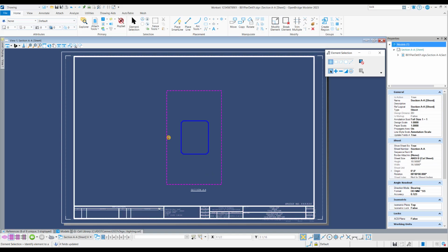After we adjust our reference scale, we'll want to make sure that we go in and adjust our annotation scale as well. So to do that, we'll open up the Models dialog box, and we'll make sure that we have first our Properties window open. Mine is docked to the side, but if you don't have it docked in the primary group, you can open up the Properties there.